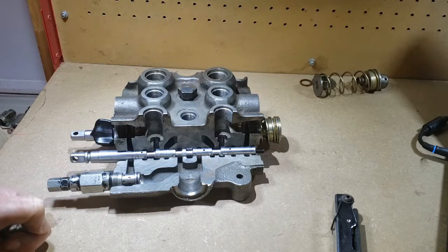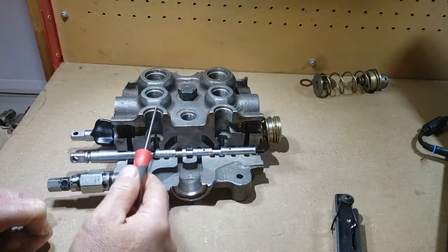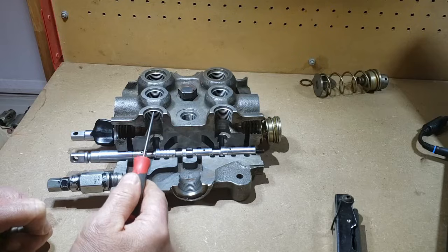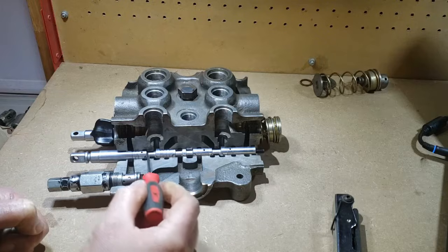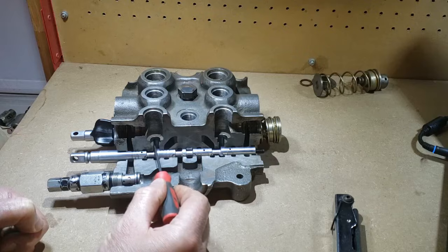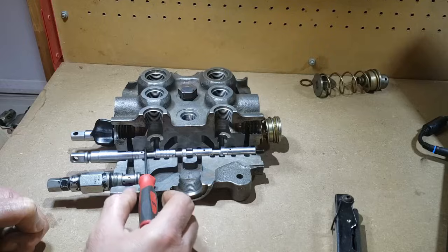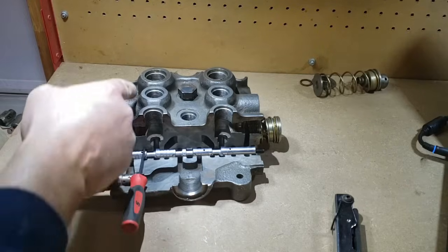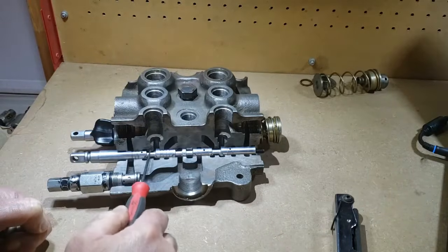So all the oil is coming out of this one work port, but it's teeing off, and separate hoses going to left and right cylinders. So that loader frame is going to be going up. Oil is going to be returning from the rod end of the lift cylinders. It's going to come back in this work port, get around this notch, which is now open to tank, which is right there. So oil returning can come in here, and this notch is now opened up across this passage, and that oil can dump into this passage when it runs back across in the housing and back to the return. So that's how our loader frame is going to go up.